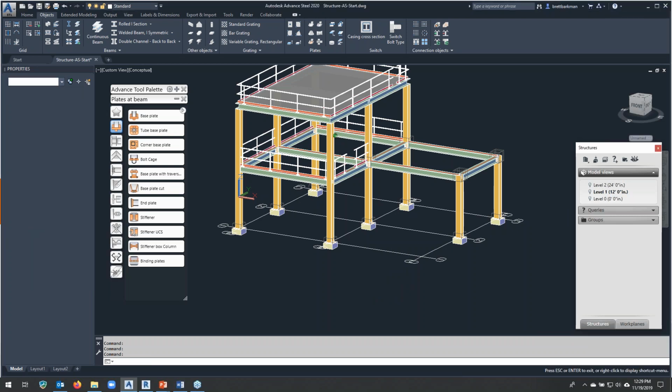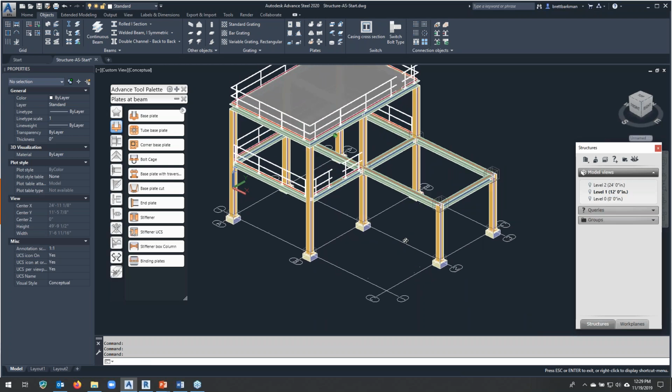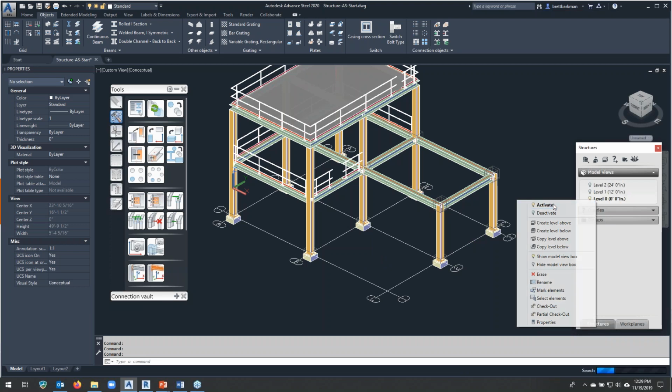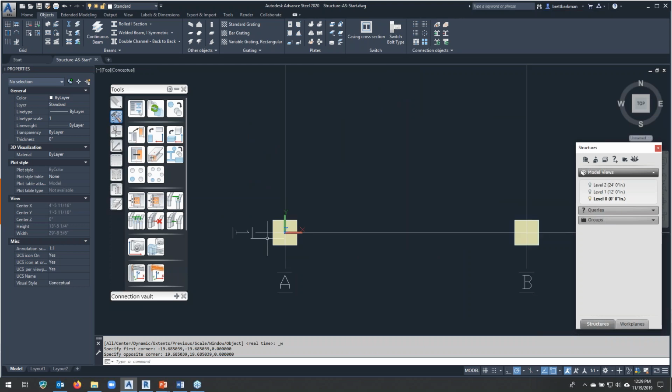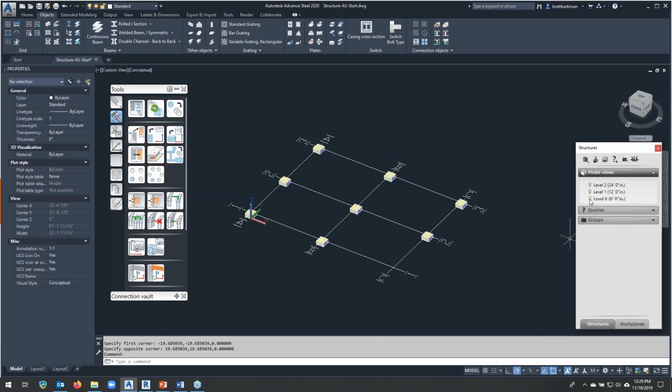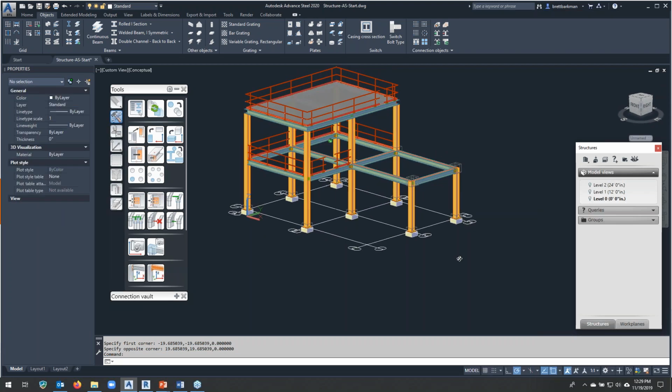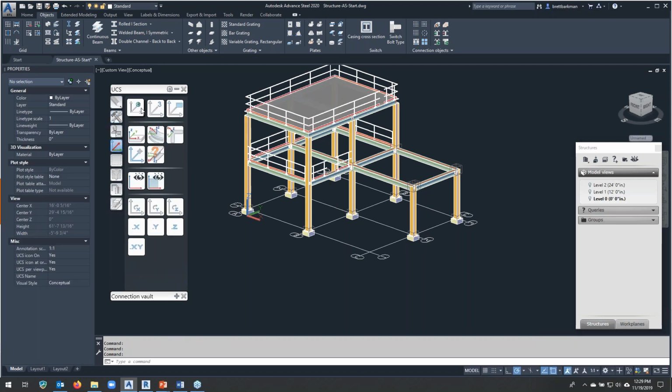All right. Moving on here, next element I'd like to create is a stair. Before I do that, I am going to reset the UCS because it is still tied to level 1 and we're active on that. You can also deactivate that level, or I can activate level 0 and that will make sure that the stair is associated with the floor. So why don't I do that? So I activate level 0, reorbit. We'll also turn off all the visibility, which essentially makes the model visible. We'll also go to the advanced tools and we'll reset the UCS back to the world UCS.